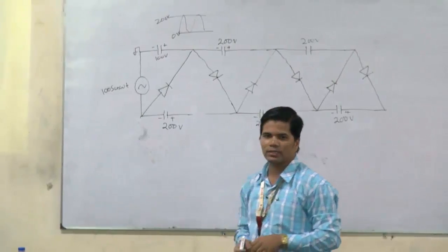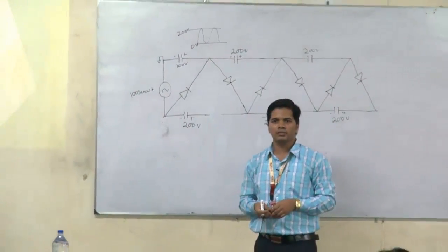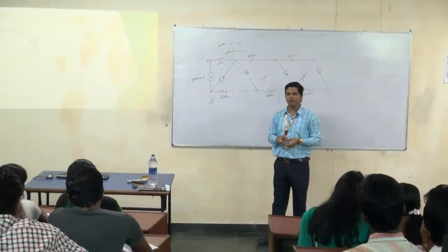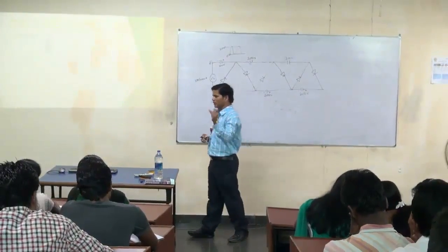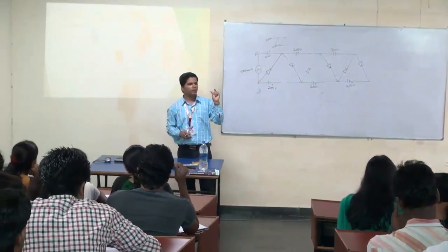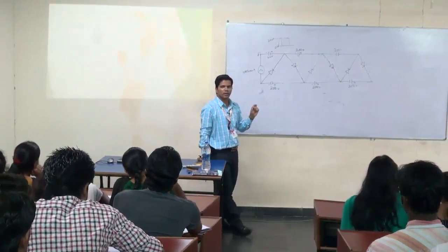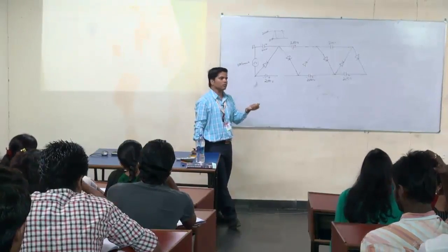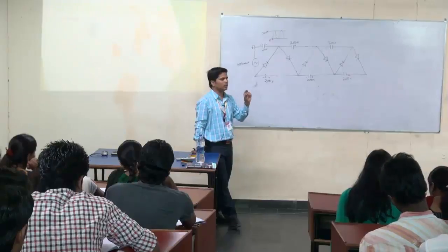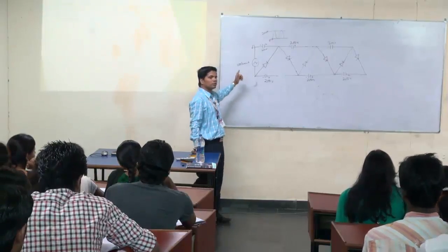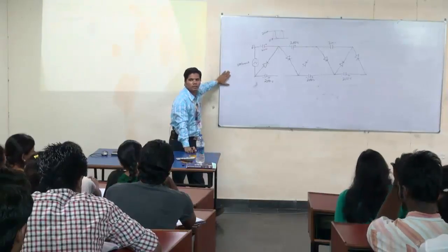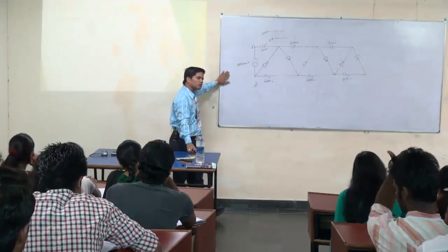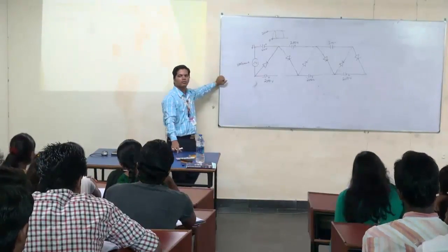This is most important. Listen here: as we are working at very high voltage, we definitely cannot use a normal capacitor. Whatever capacitor we use should be of very good quality, and whatever diode we use should also be a very good quality diode. We should not use any lossy capacitor. By default all capacitors are lossy, but we have to have a better quality capacitor, because we will use these in a high voltage circuit. It should have the capacity to bear that much voltage, and the peak inverse voltage of the diodes and all these things should have a better and higher value.